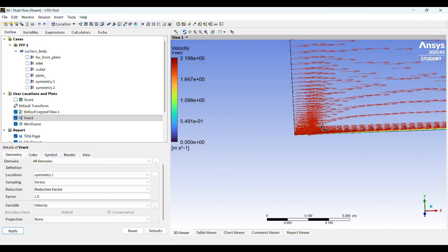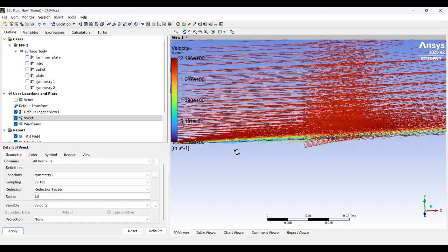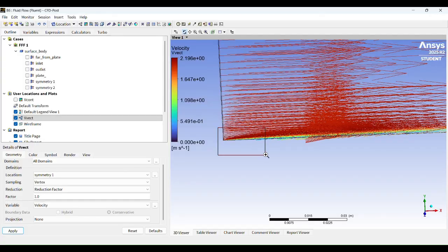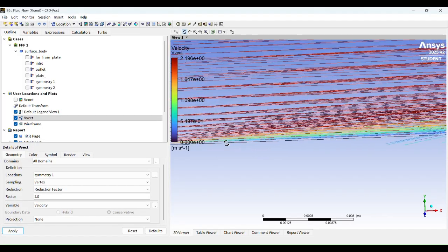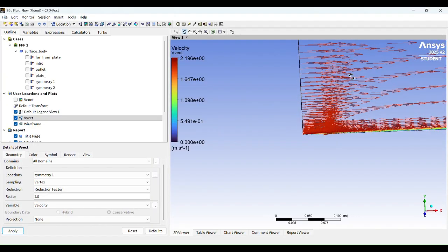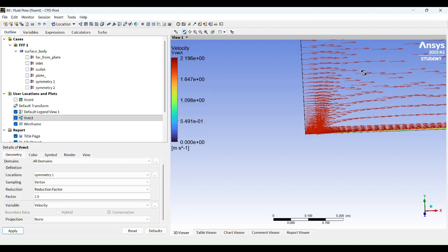So the reason the arrows are weird is because my mesh is weird, but I basically wanted as many arrows as possible in this frontal region here, and for some reason it wouldn't let the general mesh work with a specific inflation I did on the bottom layer.